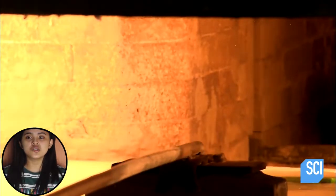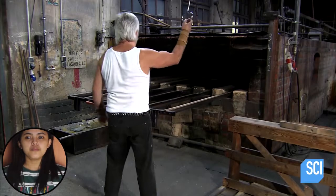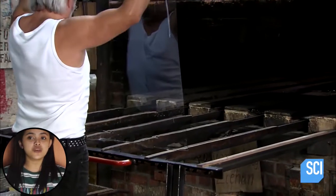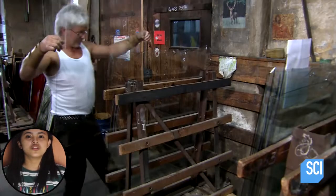The flat sheet goes into the annealing oven for a gradual, controlled cool down. This relieves stresses and prevents cracking. The flattening master's assistant finally removes it from the annealing oven and performs a visual inspection. The last step is to cut the edges straight.